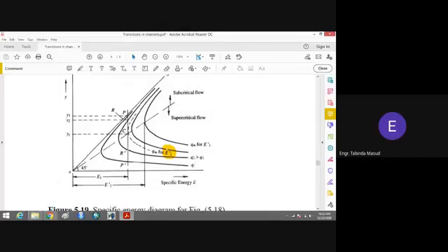You come to this point R, and you can see that at point R the depth of the flow is greater than the depth of the flow at point P. This shows you that when the water flows from the channel into the contracted section, the depth of the flow will increase. If you further increase the contraction of the channel, then what will happen? This point R will move towards point C in this dotted curve, where you have the critical depth of the flow.